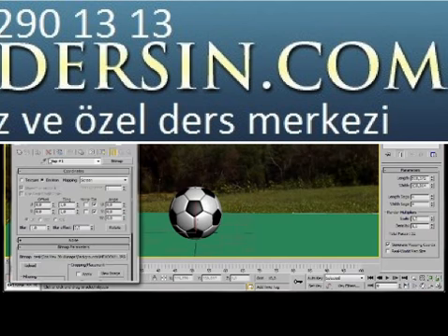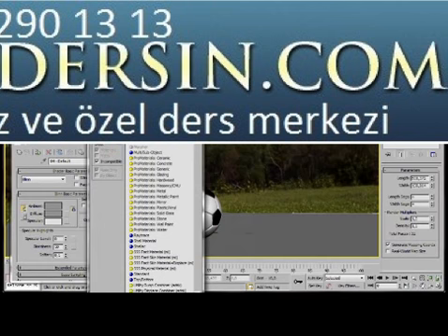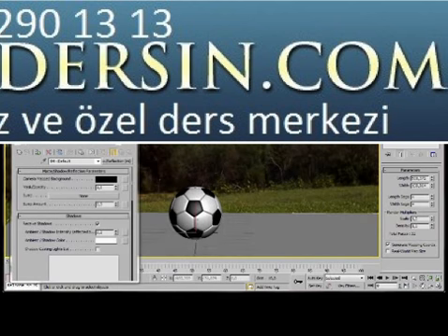Open the material editor. Let's select the next empty material and we'll drag it to the plane. Then we'll go back to the material editor, click on Standard, and double click on Matte Shadow Reflection. Here we are. You can see now we have a black circle in the material slot. If you look down here under Matte Shadow Reflection Parameters, we can see there's a black colored box, and next to it there's a very small settings box.